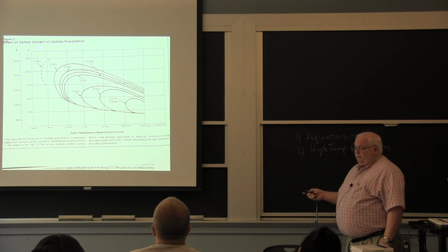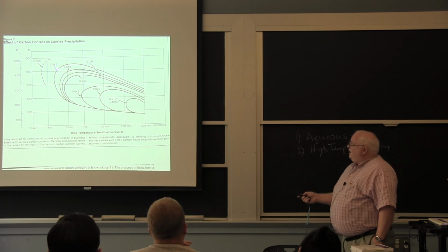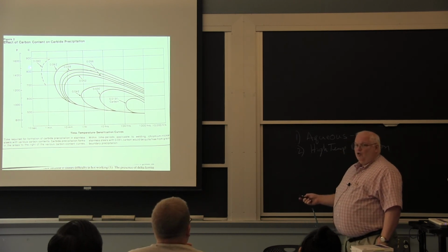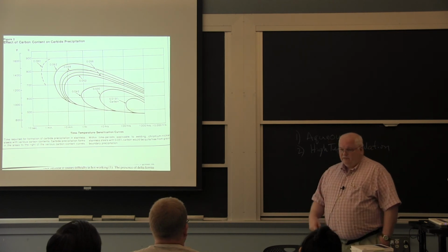Wow, it takes less than a minute. And so you can be welding stainless steels, and you could get the low chromium heat affected zone, which would just be eaten away in a lot of acids. Yes?